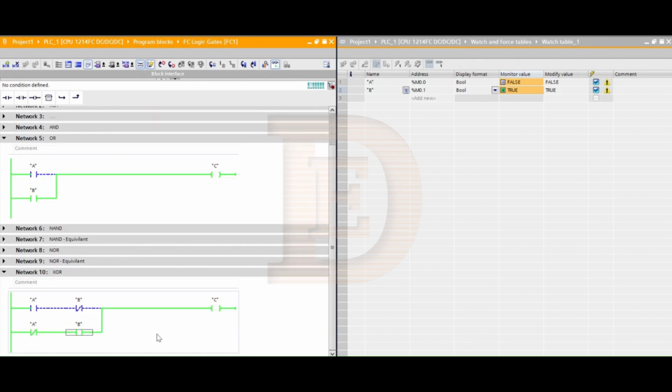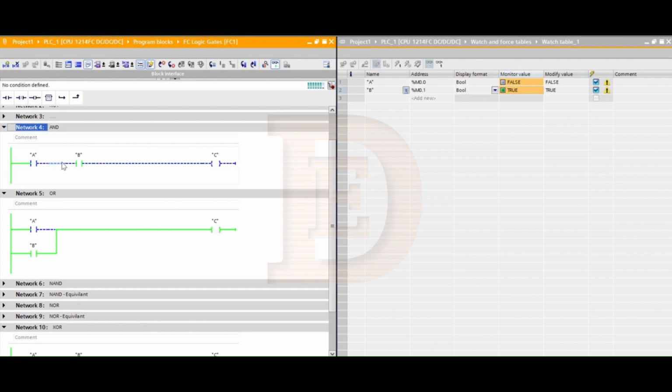So basically the whole thing goes back to series or parallel. If we have normally off switches in series, that's the AND gate. If normally on switches in series, that's the OR gate. And then we either put in not here or not here. We either put in negation on these guys or no negation on these guys. It's all combinations of these two shapes.